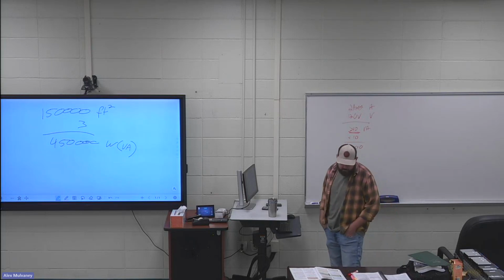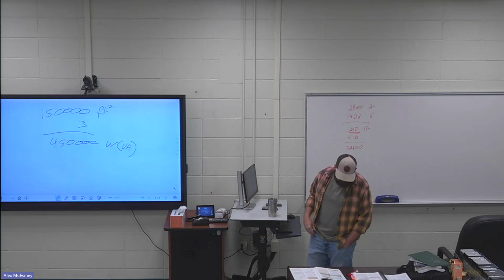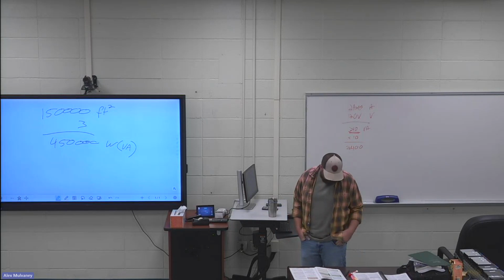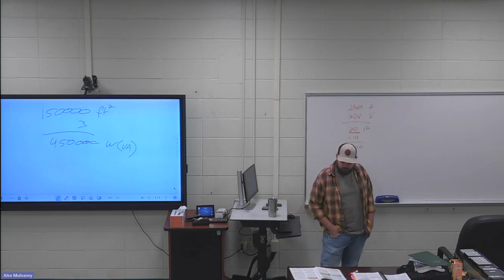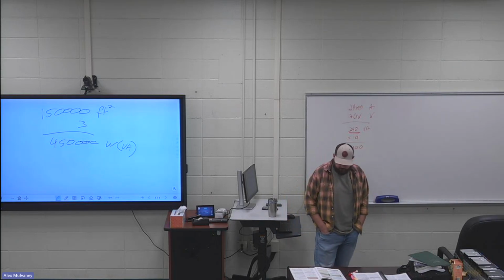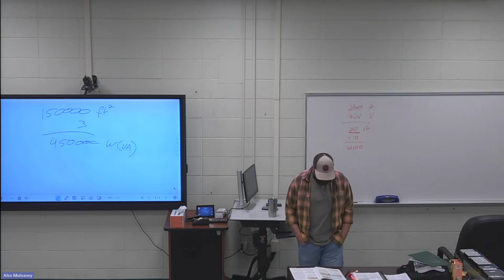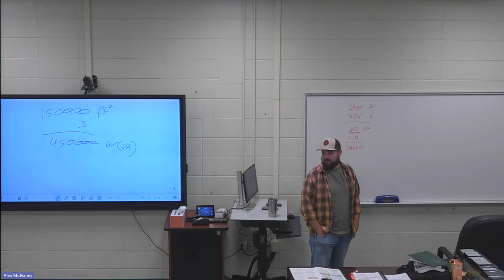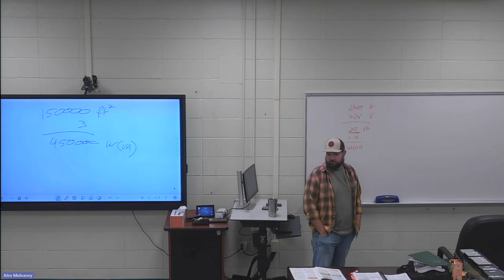Down all the way at the bottom left, online test question, they did the 3-phase calculation. All the way in the bottom left, right above that note, all that's highlighted. The maximum load that can be supplied by a 20 amp, 208 volt 3-phase circuit is determined by multiplying the 20 amps by 208 volts by the square root of 3. So if it says 3-phase, you're multiplying by the square root of 3.